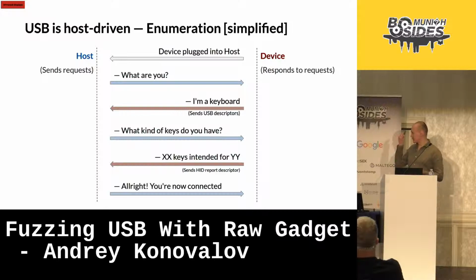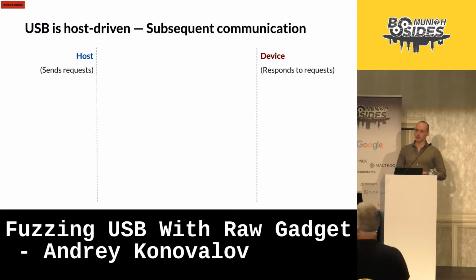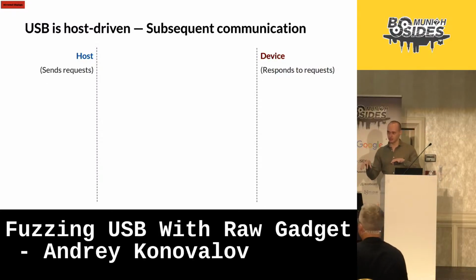All right, the key part here is that the device only responded to requests from the host. And this is actually how it works. So, for example, if you plugged in a keyboard and started pressing keys, the keyboard cannot just tell the host by itself that this particular key is now pressed. The host needs to ask for it.